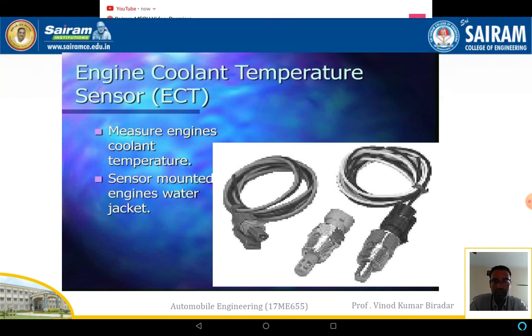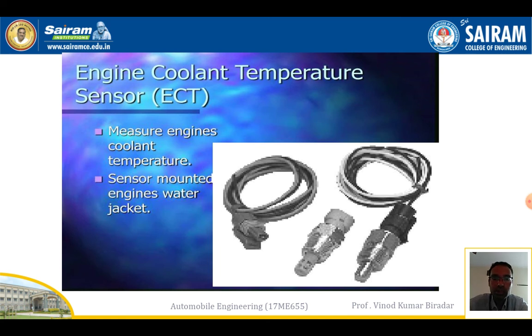These are the systems which are used. Where are the fuel injectors located? The fuel injectors are located in the head of the engine and threaded into the combustion chamber, with the nozzle inside. Normally all fuel injectors are fitted in the head, near the engine.